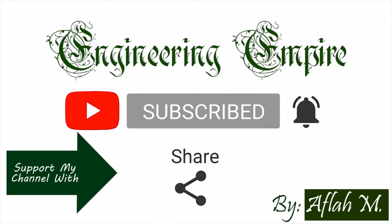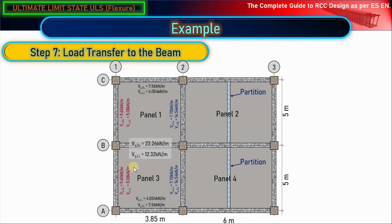Hello, welcome back. In the previous video we stopped here, where we have seen the load transfer of two-way slab. From panel 1, panel 2 and panel 3, we have seen that this much load is going to be transferred, and the dead load from this slab and this slab, the sum is 23.26, and the live load will be here 12.32. In the same way, I have calculated the load transfer from panel 2 and panel 4, and my final result is this.